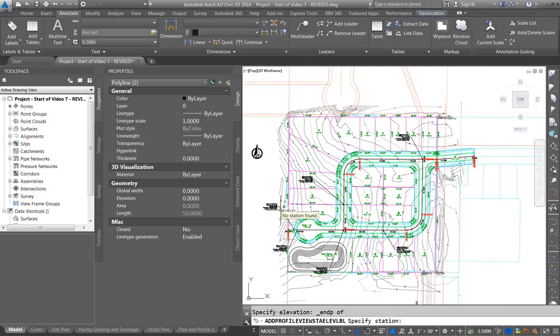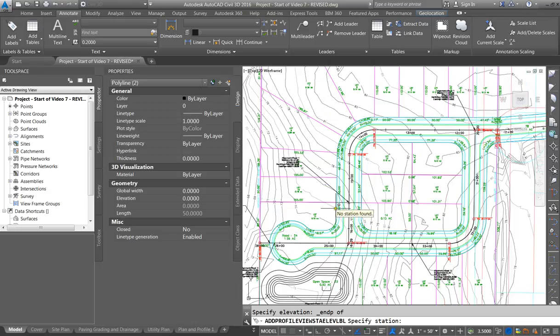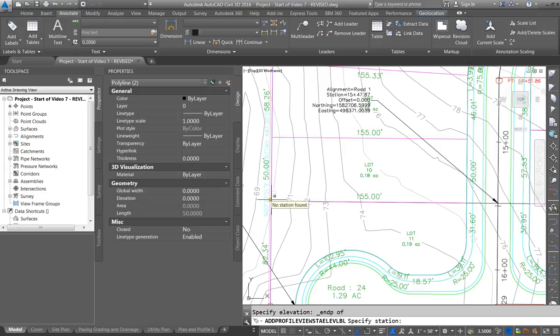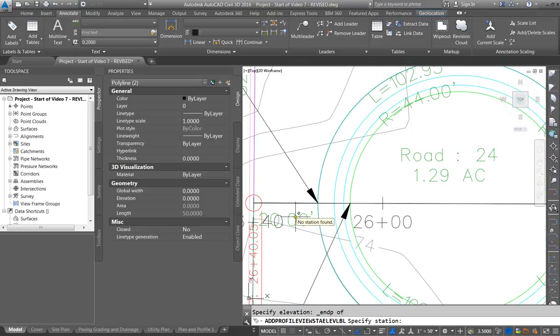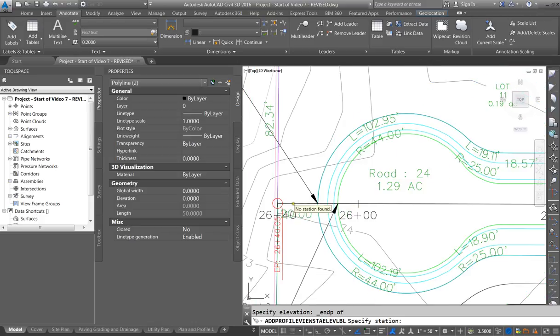All right. So we have to remember that because we're going to grade this all the way down. So we need to grade it down to this low point, and we have to think about, okay, we have 150 feet. We want to use 100 for the lot, and then we'll have 55 feet left to grade back to natural ground. So we can have the elevation in the 80s if we want, but here's the other problem. We have to get this point low enough that we only have 20 feet from the back of this right-of-way line down.